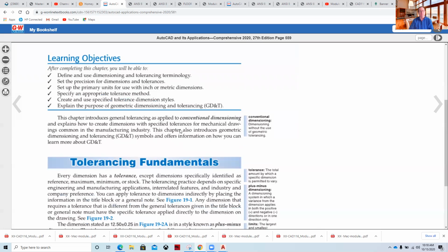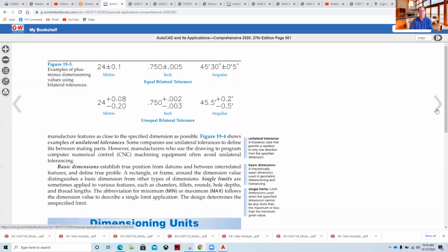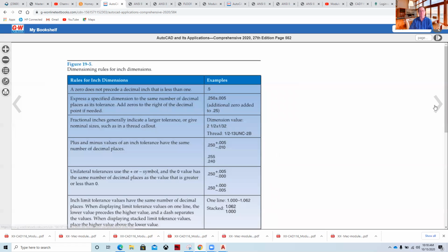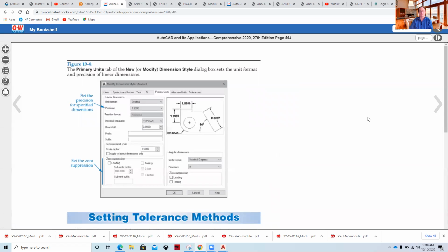And there is one drawing on the splash page for that, to be able to create something that is very accurate, 2.5 inches plus or minus 0.005. A human hair is about 0.003, 0.004. So it's very precise as far as how these parts are to be created. And that's the kind of precision that is typical in today's modern digital manufacturing.